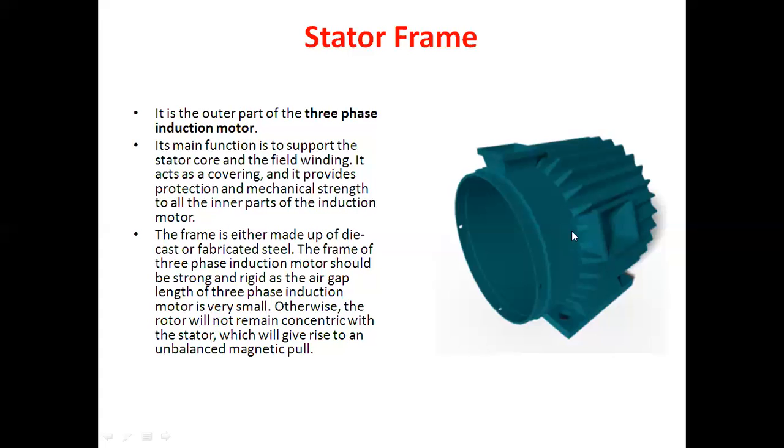From that pictorial view, it is seen that it is acting as a covering, and it provides protection and mechanical strength to all the inner parts of the induction motor, and it is generally made of die cast or fabricated steel. So this is the general purpose of the stator frame of a three-phase induction motor.